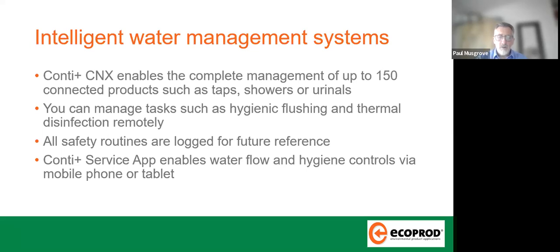Why would you want a water connected site system? It fundamentally gives you control. It helps the site management team understand their building, not just from a water perspective, but also from a heating perspective. It can identify and improve the water hygiene, which is very important to stop the buildup of biofilm within your building. Biofilm is the cause, or partly the cause, of debris in the water, feeding bacteria, which then can lead to Legionella outbreaks.